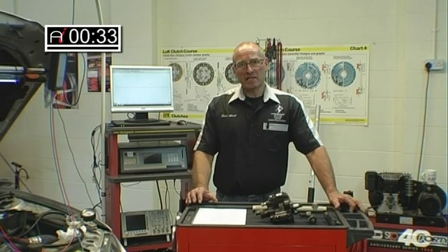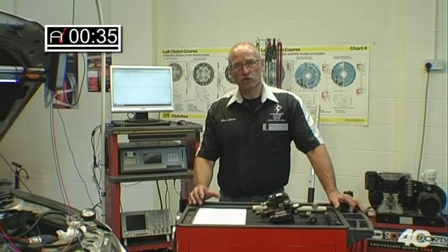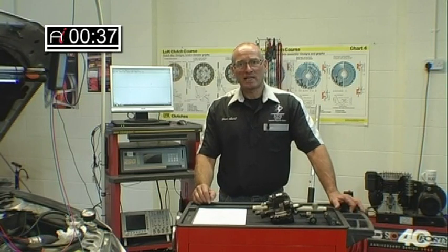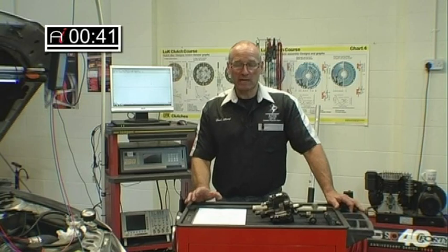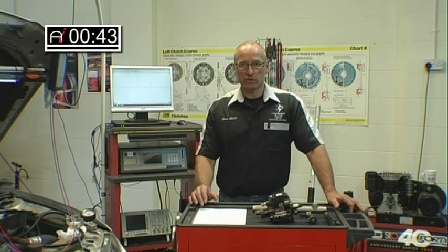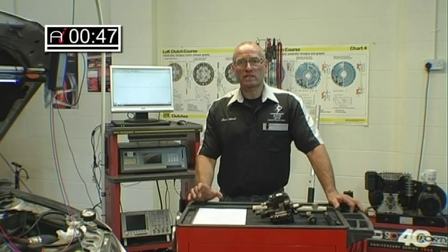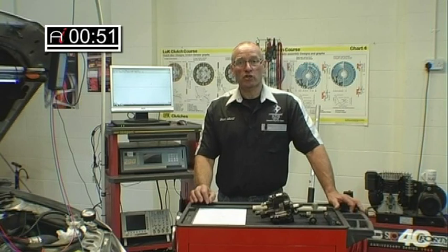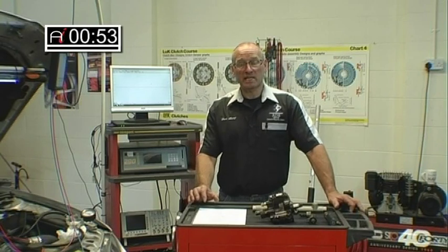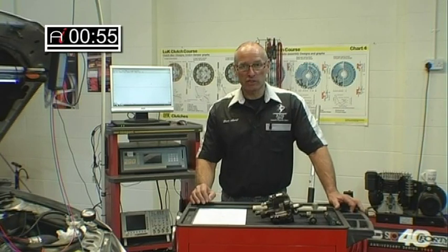I'm tempted to say that the diagnostic approach using serial communication is an invitation to speculate only. And by that, with the greatest respect, I mean that those faults stored in the computer can be caused by a whole series of events which do not directly relate to the cause of the problem. In other words, you may be looking at symptoms, not cause.